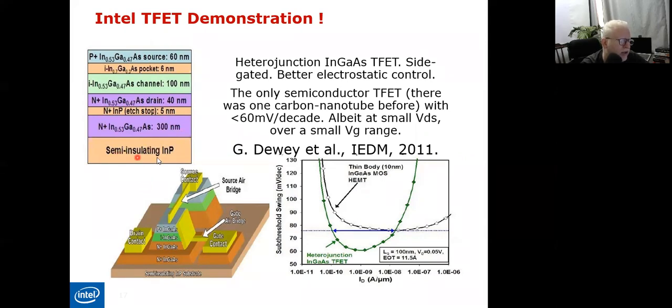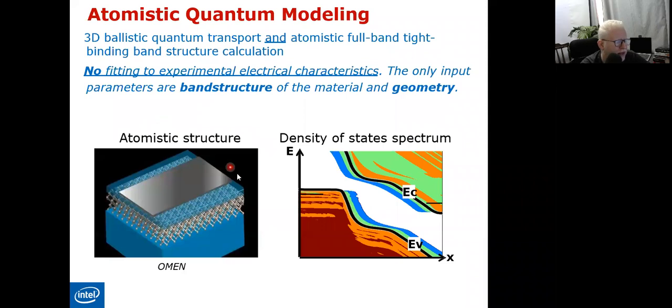It's implemented on a semi-insulating substrate of indium phosphide, and then you have your structure as a PIN structure. So this is the N region, this is the I region, and this is the P region, as you can see. So it's an NIP junction or PIN junction. You can demonstrate it. However, we have a set of materials with different properties and maybe different job descriptions in the structure. And this is also a fabricated structure.